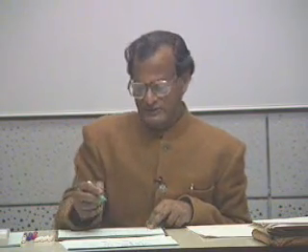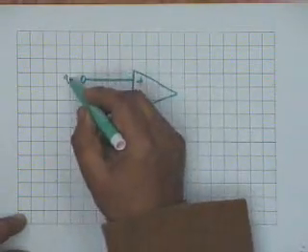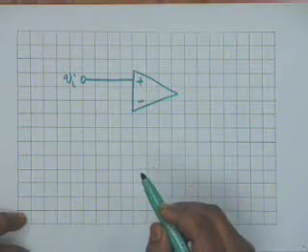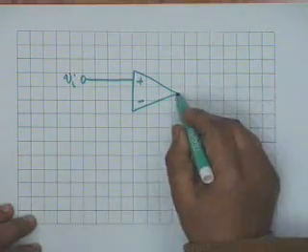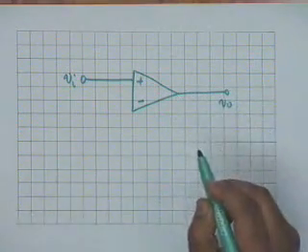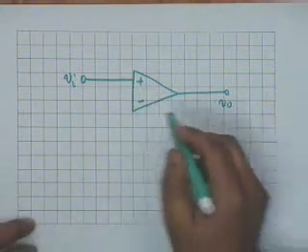If you want a non-inverting gain, then as you can guess, our input shall be applied to the non-inverting terminal. Let us draw it up to show this clearly. Suppose there is a voltage Vi here. What we want is a non-inverting gain. In other words, we want a V0 which is equal to a positive quantity multiplied by Vi.